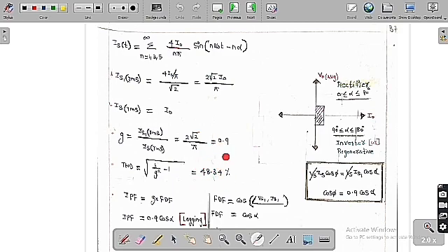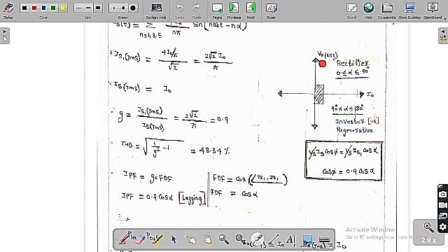You can see clearly, irrespective of alpha, G is equal to 0.9 and THD is equal to 48.34%. Then I have already told you the average output voltage and the average output current I naught. From 0 to 90 degrees, V naught average is positive and I naught is also positive, so this is the graph we get in the first coordinate. This is called a rectifier, meaning the power is transferring from source to load, so it acts like a rectifier, converting AC to DC.